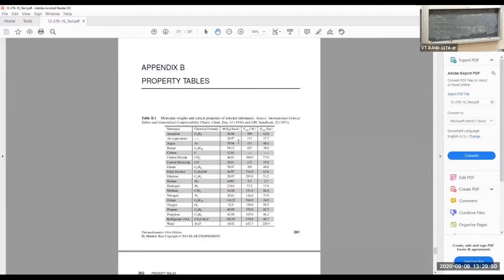Now for the units to work out right here, this megapascal has to be expressed in terms of kilopascal, so it cancels out with the kilojoule in the gas constant. So let me convert out of the mega. There's 1,000 kPa per 1 megapascal, and the megapascals will cancel out, okay? Let's put that all in the calculator and we'll see what the mass is.